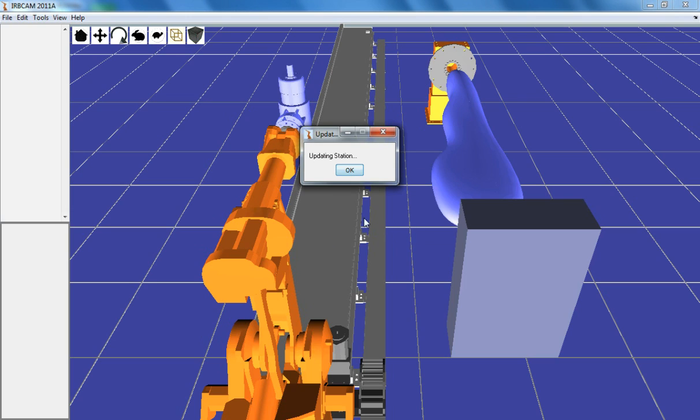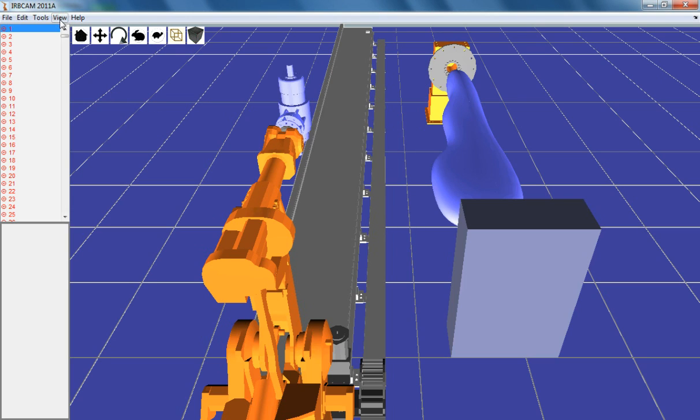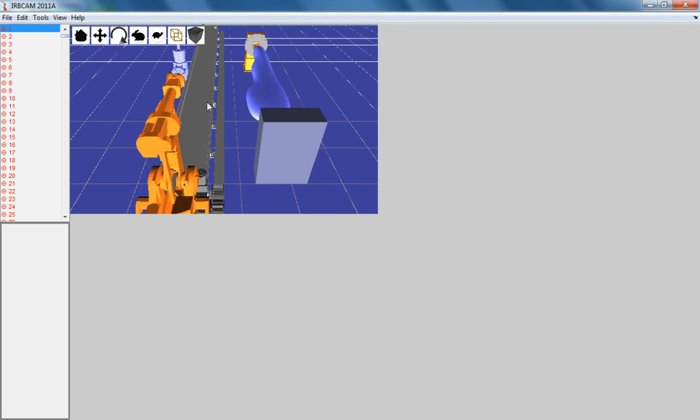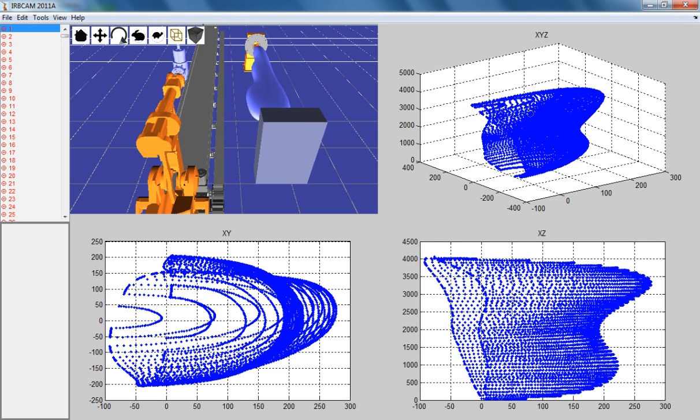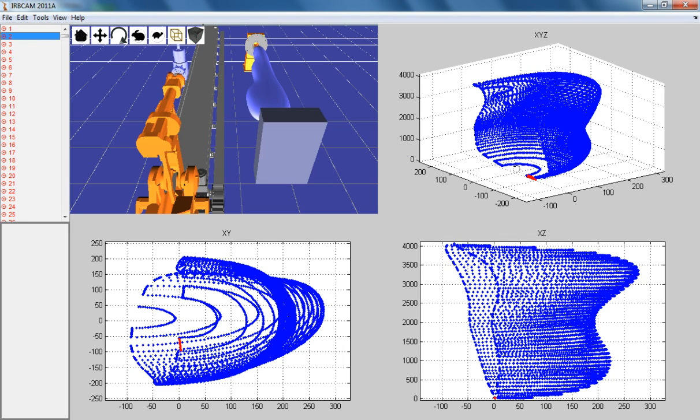Once the APT file has been loaded, we can go View, Combination View. And we see here the X, Y, Z. These are the 3 degrees of freedom of the toolpath. If we click over here on the coordinates, we also see the tool vector, which contains the other 2 degrees of freedom. So in total, this toolpath from the APT file now has 5 degrees of freedom.